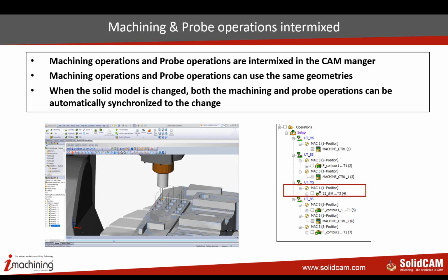If the CAD model is changed, because the probe can use the same geometry as the milling operation before it, for example the contour, then when the 3D CAD model is changed, the milling operation will be calculated and synchronized, and also the measurement cycle, the probe operation, will be synchronized. We have full synchronization.